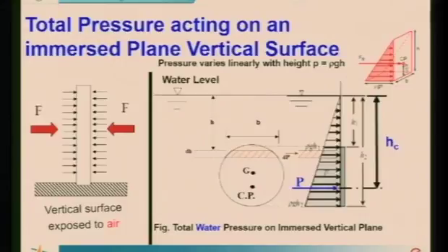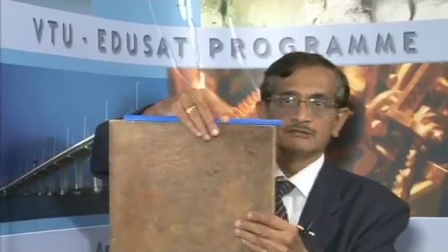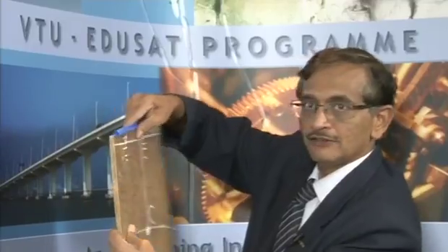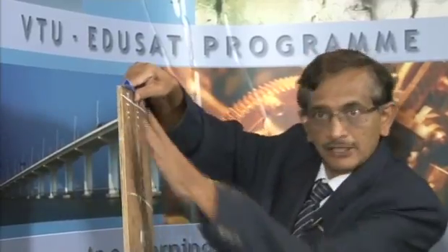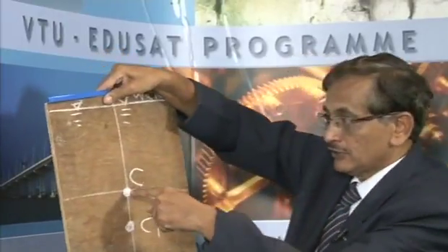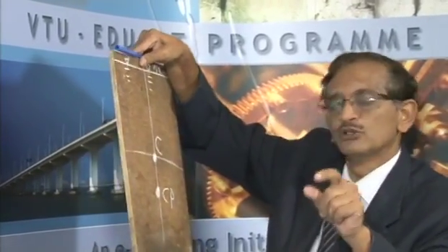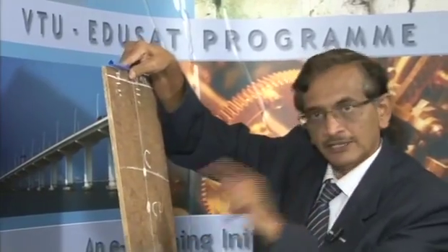The pressure prism diagram also is shown. Can you see here? It is minimum here, it is maximum here. It is quite possible that sometimes the gate and the level tally exactly like this diagram, this red diagram which you are seeing. Exactly like this, so it is tallying with the same. The water level is also here, the gate is also here. I would like to know what is the force I need to lift it. Mind it well, in that case, the centroid of the figure is here and the center of pressure is slightly below, not much, but it will always be slightly down.